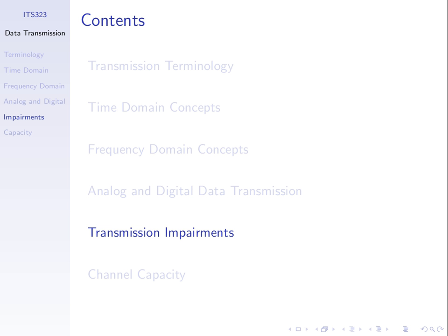If I'm talking, even with the microphone, and everyone else in here starts talking, the person at the back will not be able to clearly hear what I'm saying. Because from that person's perspective, my communication is the real communication, but everyone else transmitting is transmitting noise. So the larger the distance, the weaker the signal gets. That's called attenuation. It's a transmission impairment. It impairs our transmission. And noise is the other major transmission impairment. Other sources generating signals make it harder for the receiver to understand what's being conveyed.